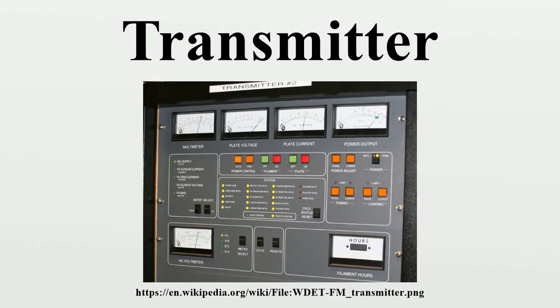An RF amplifier to increase the power of the signal, to increase the range of the radio waves. An impedance matching circuit to match the impedance of the transmitter to the impedance of the antenna, to transfer power efficiently to the antenna. If these impedances are not equal, it causes a condition called standing waves, in which the power is reflected back from the antenna toward the transmitter, wasting power and sometimes overheating the transmitter.